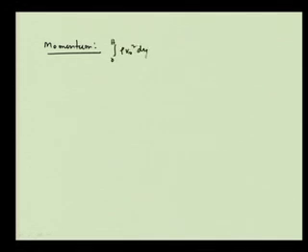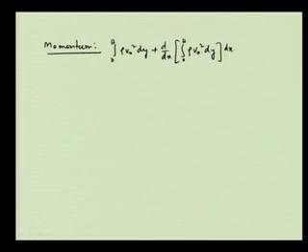Similarly, we can have the momentum out, that would be the integral from 0 to h of rho v x square dy plus d dx of the integral from 0 to h of rho v x square dy, and whole into dx. That is the momentum out.